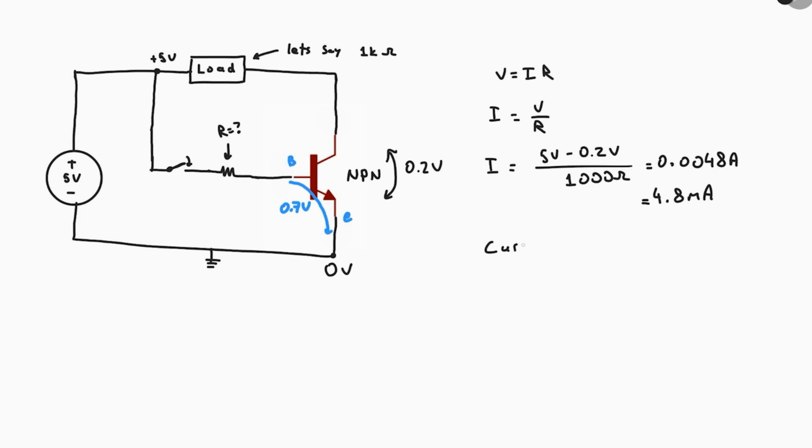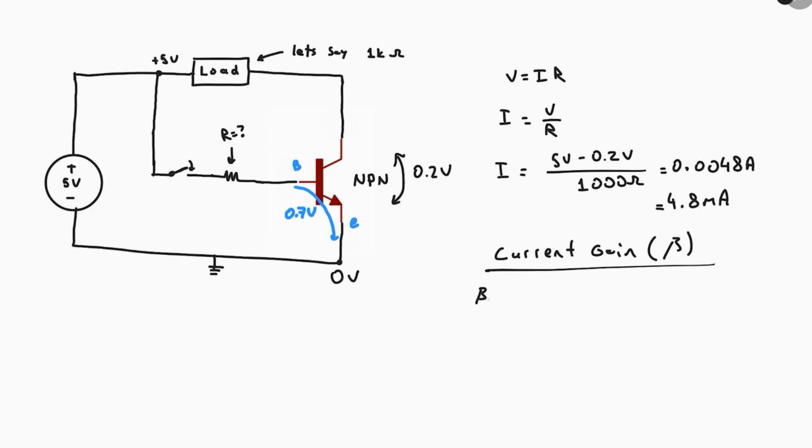Transistors have a current gain, beta. In this case, my transistor's current gain is, let's say, 15. So you can put 15 times less current here and 15 times more is going to go through the transistor. With that information, we divide the current we found by 15. So we have to drive this much current through the base to turn the transistor fully on.